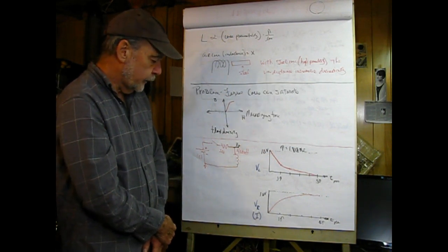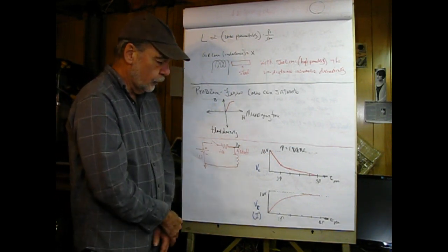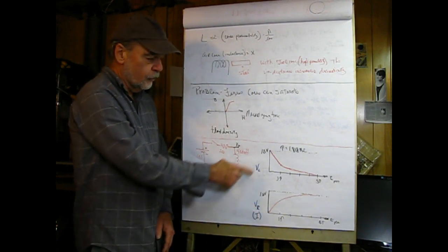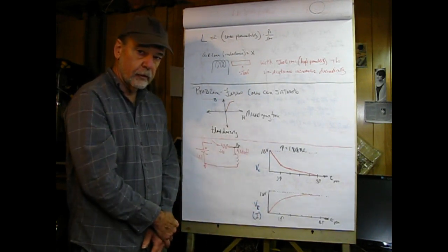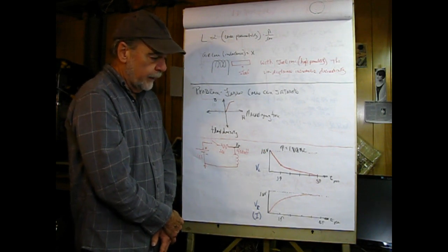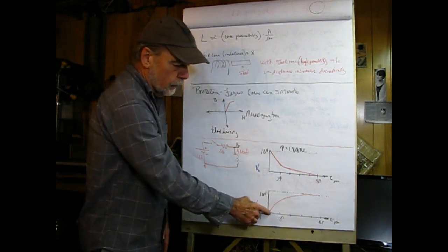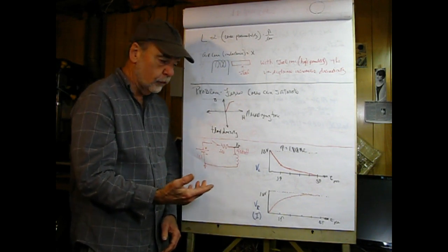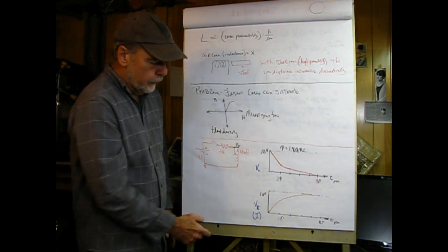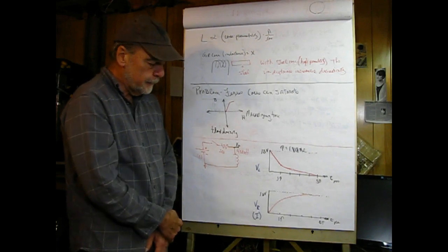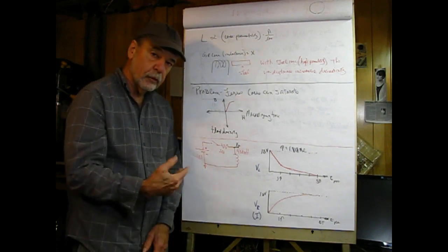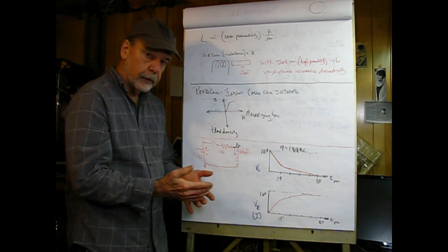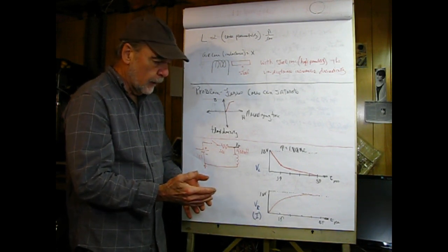Now if we take a look at the voltage across the resistor, what we see is that it initially starts out to be 0, because all of the voltage is across the inductor. As time passes, the voltage across the resistor asymptotically approaches 10 volts. The shape of the voltage across the resistor is also the shape of the current, due to the fact that resistors are linear and Ohm's law applies.